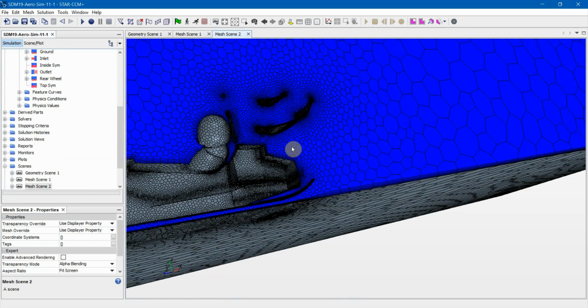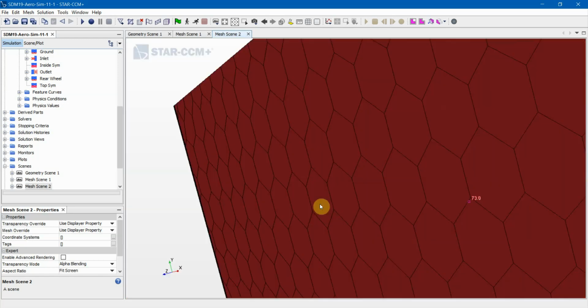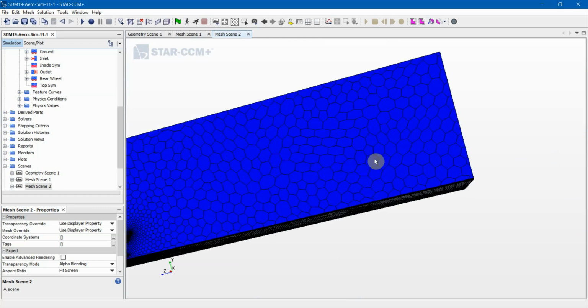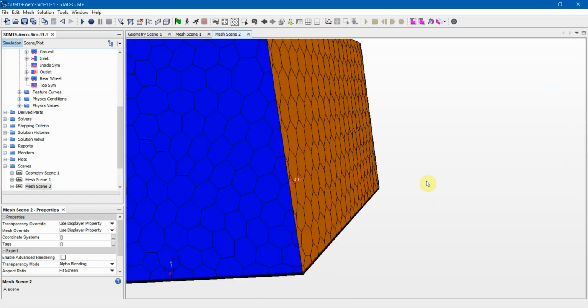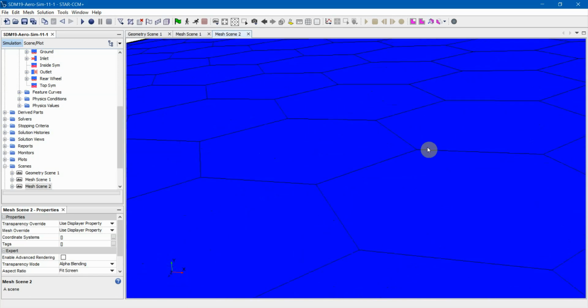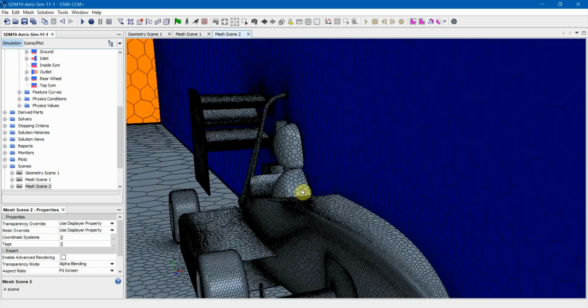Also, if you can figure out how to refine by volume, so you'd want half the car length in front, full car length in back, to be further refined, because I know I'm wasting a lot of resources on these cells. They could be coarser, and then closer up they could be finer. So anyways, a little aside there.